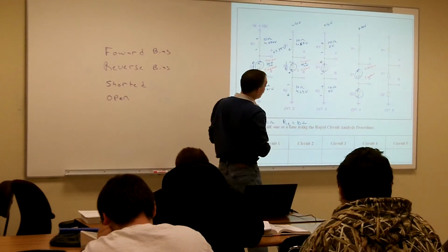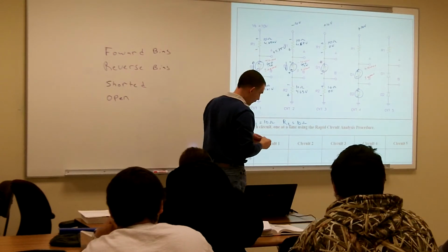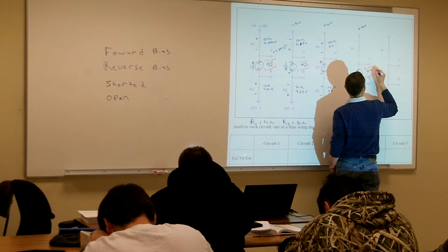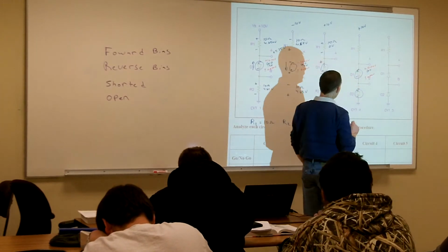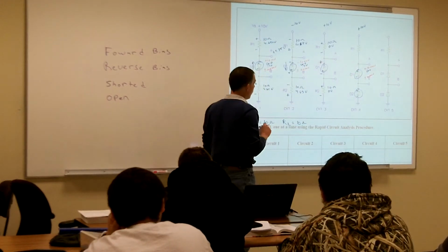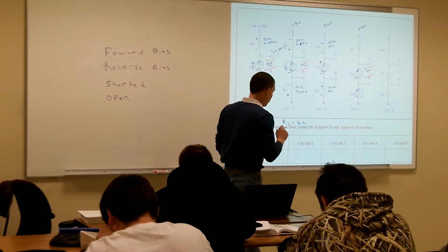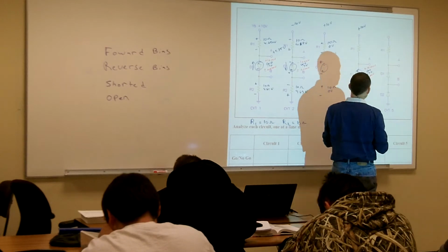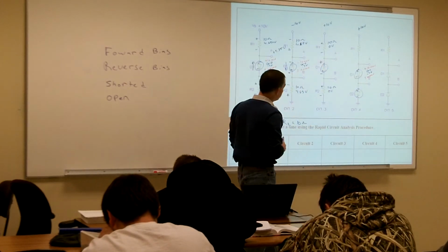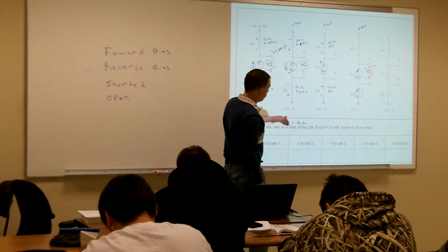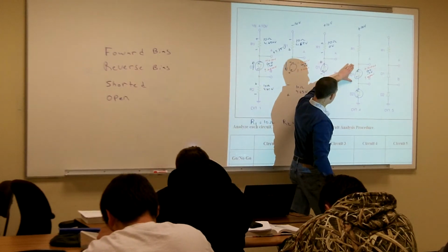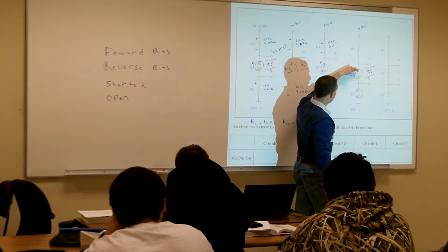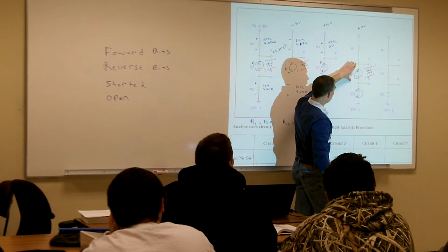So is that diode a go or no go? Go. That one's the go. And it's still going to drop its voltage first. And what is it going to drop for a voltage? 0.7 volts. Okay? So now that diode we're going to consider a go. We're going to keep that in the circuit now. And so we know that that's going to drop 0.7 volts.